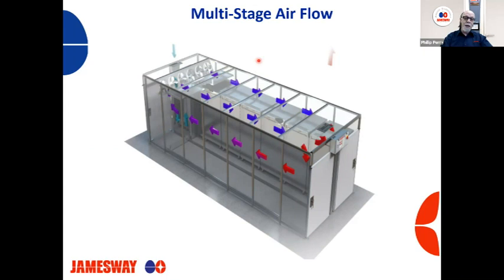One thing I just want to point out is that we want the air that enters controlled, and we want it controlled as it comes out. If we don't have control, if the room is negative, then the machine has to pull this air, and if the room is over pressurized, then it pushes air through the cabinet, and this really interferes with the distribution of the air. The same way with the air as it exhausts, it just wants air available at its needs, and it just wants to be able to exhaust it. It doesn't want to have any interference with the intake and exhaust.